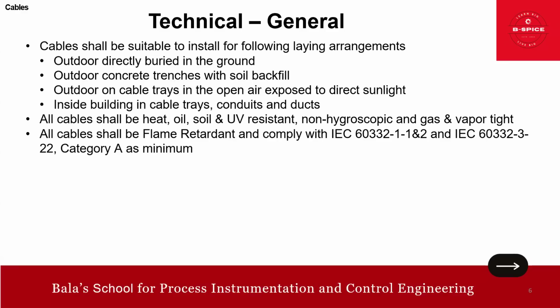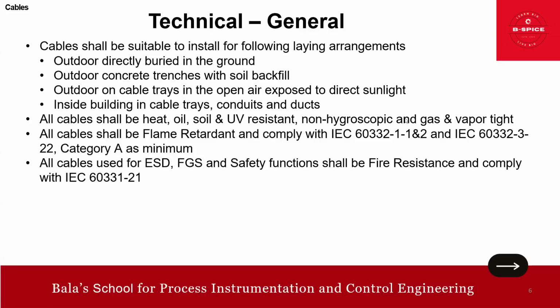So flame retardant should comply with IEC 60332 Part 1, Section 1 and 2. Then IEC 60332 Part 3, Section 22. Okay, so that is a point, flame retardant.